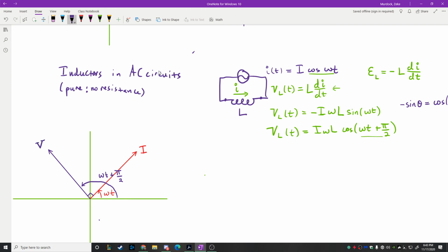Now, according to these equations, the current phasor tells me that they're rotating in the same direction. The rate at which they rotate is given by omega, and the voltage phasor is always going to be at least 90 degrees ahead, basically, so that we can say that VL leads the current by 90 degrees. We use 90 degrees when we say it here, but just remember that in the equation, we'd have to put pi over 2, right?